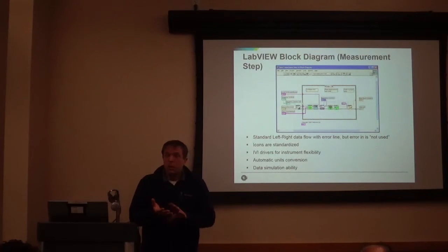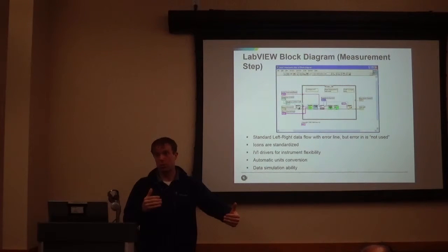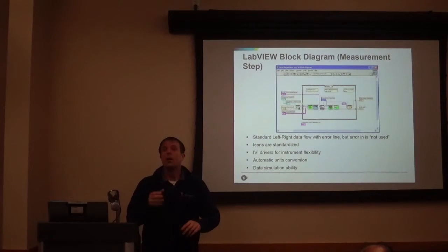So as part of the build process, you can define it and say, for all of my code modules, and we're gonna call all of your code modules LabVIEW code modules for now, you can remove the block diagram from all your code modules as you deploy, and put them into the TestStand deployment. Which means you can run your LabVIEW code, but no one can edit it because the source is gone. What about the sequence?